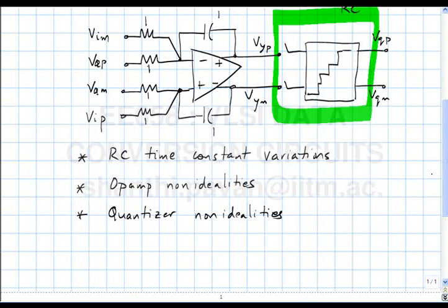Please recall that on an integrated circuit, if you make 100 resistors, all the 100 resistors will almost be equal. However, they'll all be off from what you intended to make by some random number, right? Typically, the fab tries to bound it to plus minus 20% or so if you're lucky. Sometimes it will go over a factor of 4, in which case you have to make sure that your design is robust enough, or you do have some adjustment to bring the resistors back to some reasonable value close to what you want.